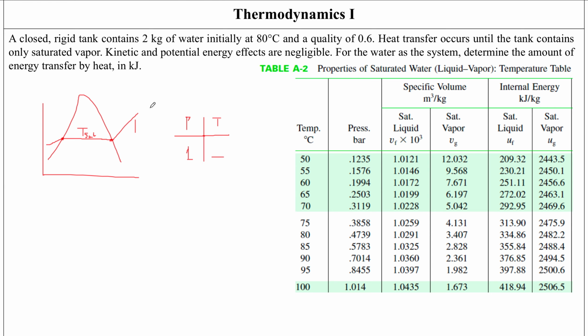If you've got a given temperature that is higher than the saturated temperature, then, since the pressure is obviously constant, the temperature is somewhere on this line, maybe here, and you should move from this table and use the superheated vapor table.